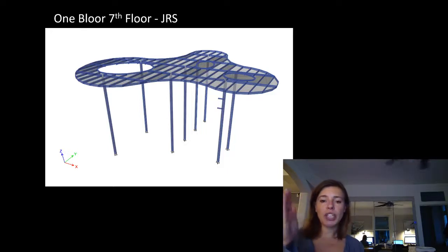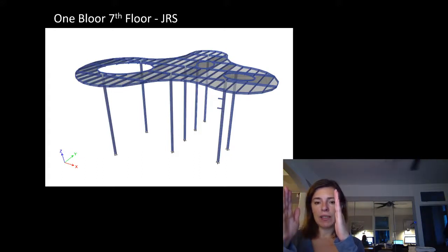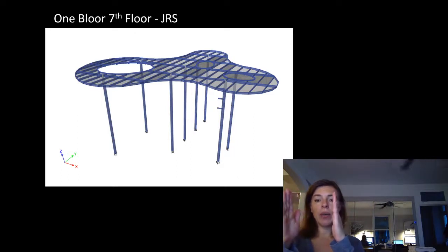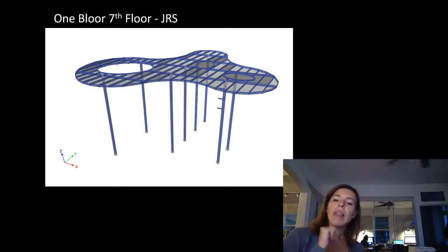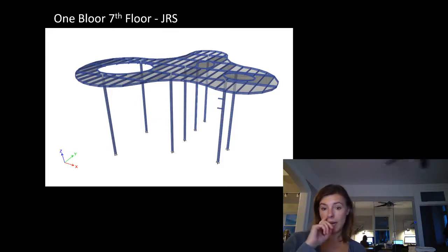If each time we check it, that deformation gets smaller and smaller, we know that it'll start to move and then finally stop, even with that full load on it. If that deflection starts to get bigger and bigger, we know that applying that load would just make the building tip over. That's something we call the P delta effect. And for this structure, P delta was a big issue. It is exactly what we needed to look at.